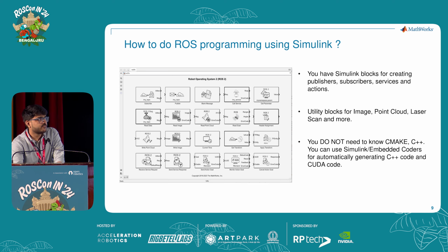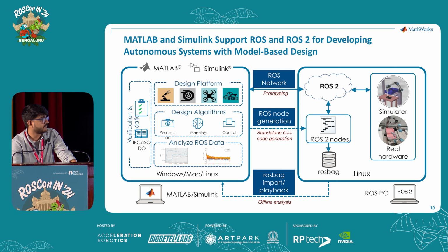So we have a huge set of Simulink blocks that you can use for creating publishers, subscribers, services, and actions. Not only that, you can use our utility blocks to process images, point cloud data, laser scan, and more. And again, with the help of Simulink Coder and Embedded Coder, you can automatically generate the C++ code and deploy it onto the hardware.